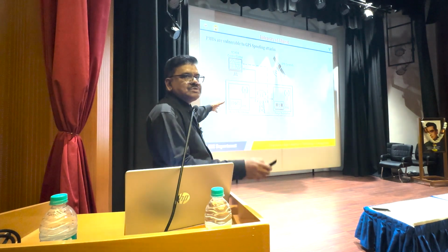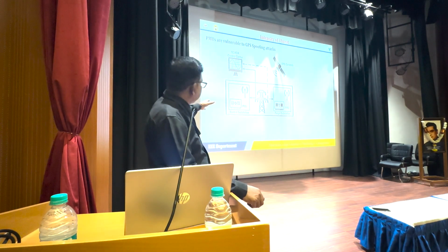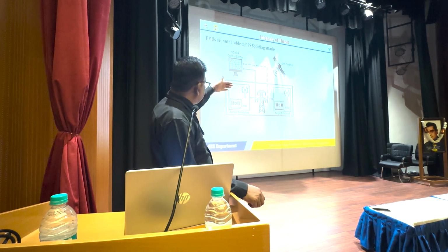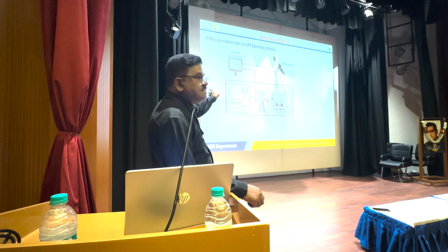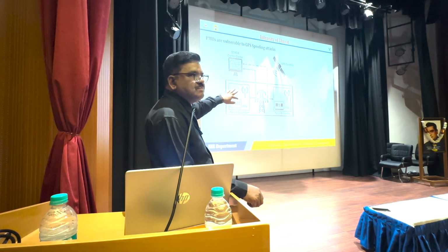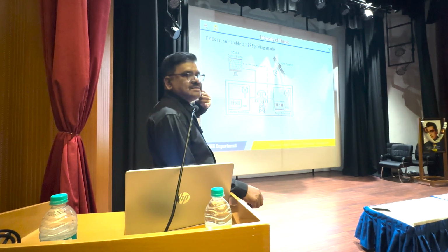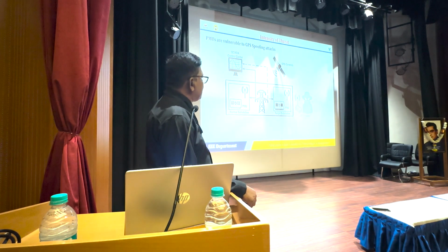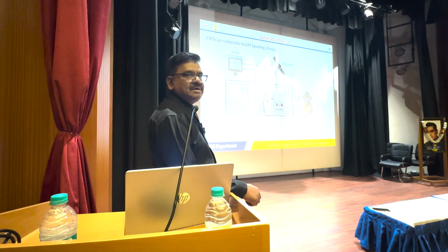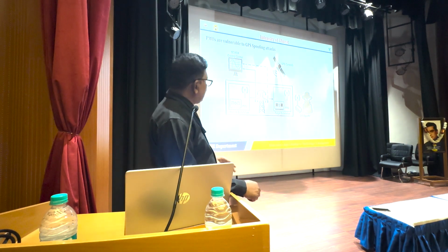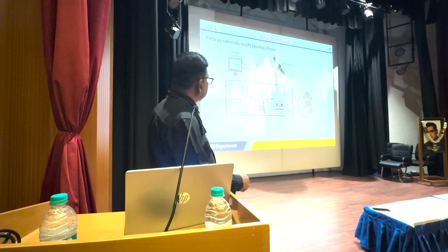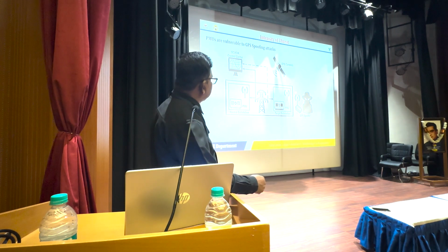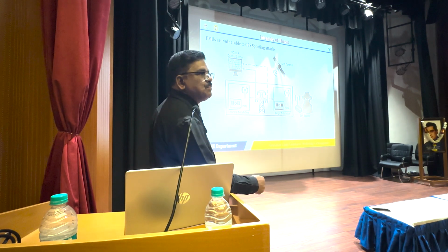Several PMUs will be located at different locations in the substation. The normal substation PMU and a second PMU are both time synchronized with the GPS satellite. The hacker will place a transmitter near the substation and target the PMU. Instead of receiving the GPS signal, the PMU starts receiving the transmitter signal. That means the attacker is fooling this PMU.